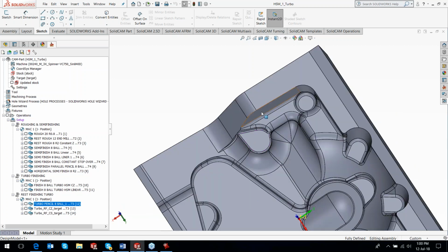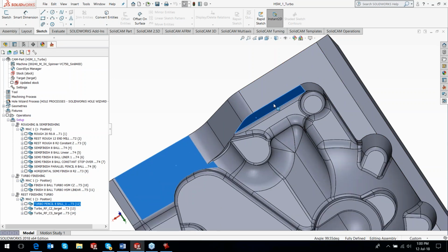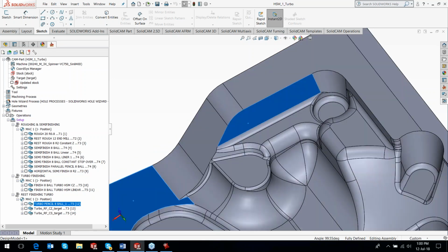If I look from the top, I have got a vertical wall here, and I have got a horizontal face here. If I'm machining this part, let's say along the Y-axis, and the software says we can support true scallop, what is a true scallop? A true scallop is a scallop that will remain true irrespective of how the surface is. So basically they will try to calculate the steepest possible surface, let's say this surface here, and they will estimate the scallop.